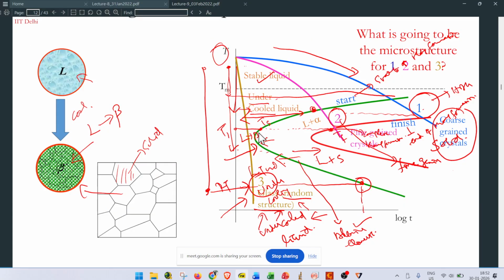So this is the time required to reach the critical radius. Once it is formed, it will start nucleation growth and microstructure formation. If the nose point is not touched, there is not enough time to form the nucleation either, so immediately this austenitic phase will cool down directly and form a martensitic phase.